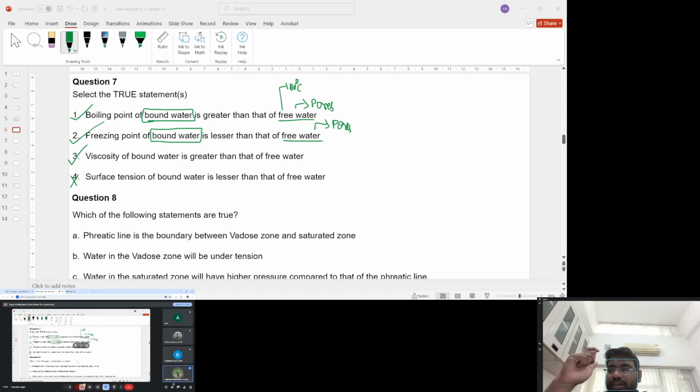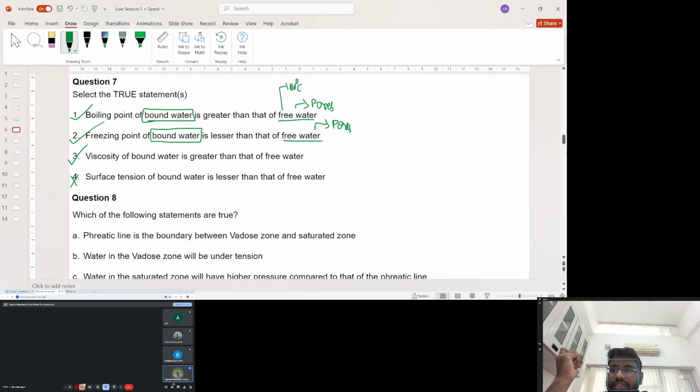Here some interesting research is going on. I would like to add this. Several people are working on freezing characteristics of soils. In this regard, it plays a very important role: at any temperature, what is the amount of ice and what is the amount of water that has not been converted to ice.